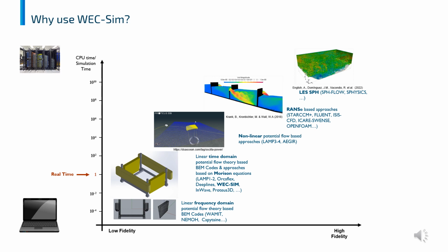When modeling a device, it's important to consider where the tool that you're using falls in terms of computational time and fidelity. A tool like WEC Sim is a time domain solver that's based on linear potential flow and incorporates nonlinearities. Thus, it's a mid-fidelity solver. It's higher fidelity than linear frequency domain models that are just direct boundary element method solvers, but not as high fidelity as LES or CFD.